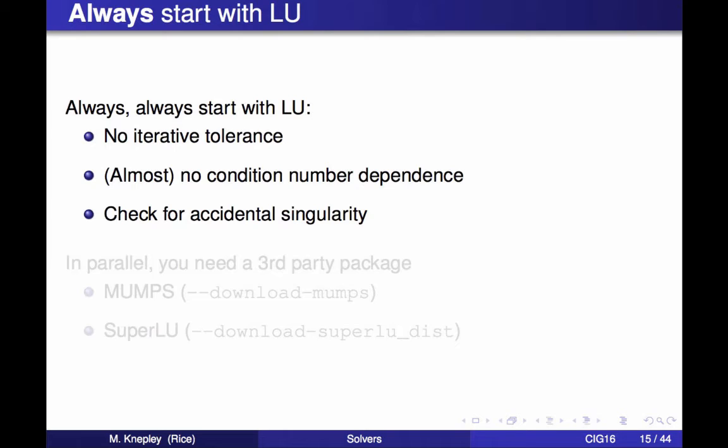Okay? So I would recommend always starting with LU. It's robust, it's completely performance predictive, you know how long it's going to take. We could actually print out how long it's going to take when you start solving if we wanted to. There's very little dependence on what kind of problem you have. The only way you can really break it is to feed it a singular problem or a problem that looks singular to it. And I'll show you that. It's also a great way to check that your problem is well specified.